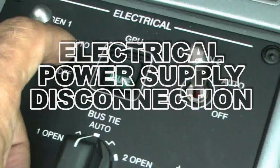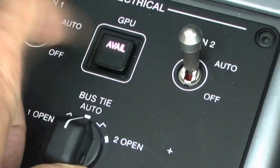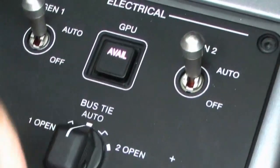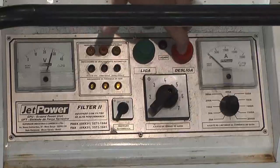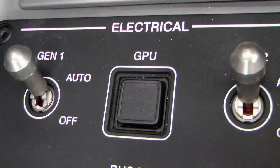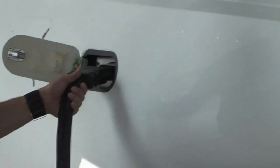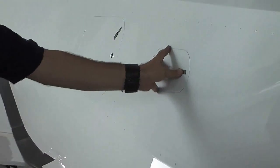Electrical power supply disconnection. Press the GPU button. The in-use indication goes off and the avail indication comes on. Turn off the batteries. Turn off the GPU. The avail indication goes off. Disconnect the GPU cable from the airplane power supply receptacle. Close the airplane power supply receptacle door.